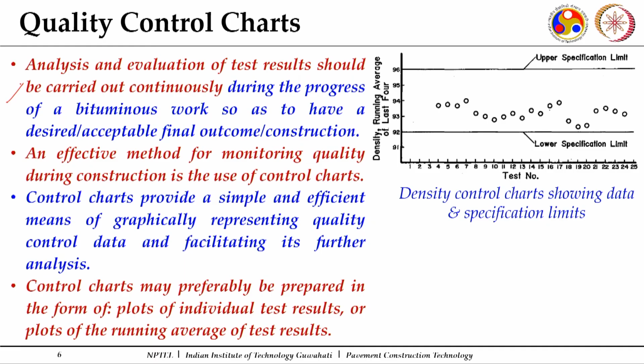Now, as we mentioned in the earlier lectures also, here we will discuss one particular aspect related to quality control charts. It says that analysis and evaluation of test results should be carried out continuously. It should not happen that once the work is completed, say one day's work, and then some checks are started. No, it should be a continuous process.